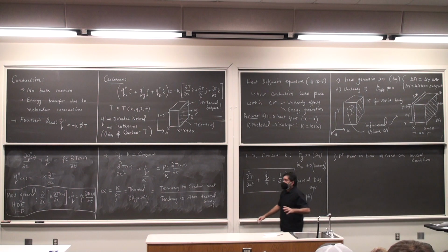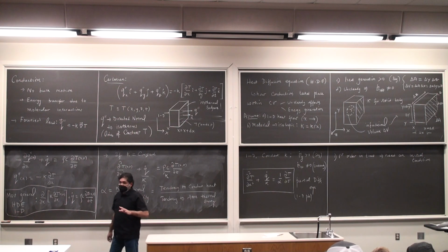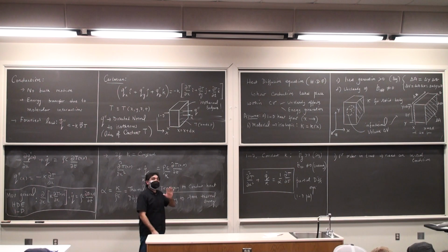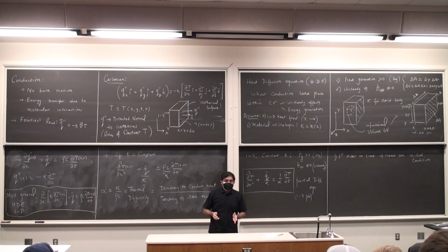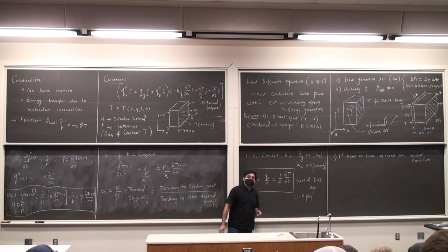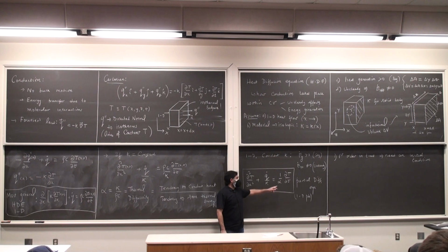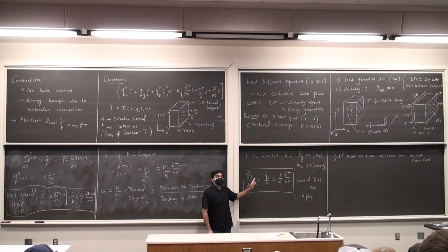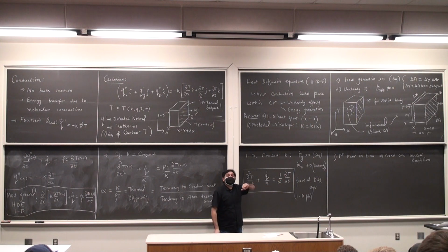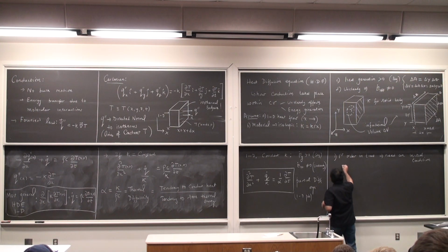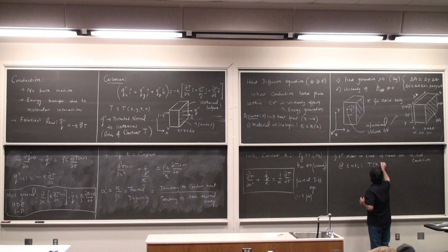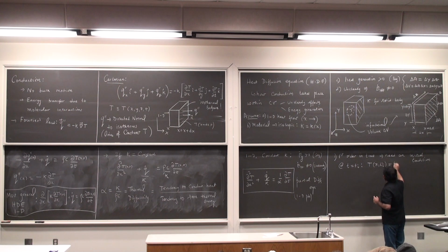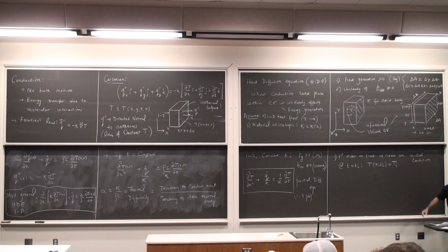What you would have done in system dynamics is you would have solved only ordinary differential equations, and they are all time dependent quantities, which means you will have to deal exclusively only with initial conditions, displacement condition, velocity condition, and so on. In our situation here, it's a little more complicated. It is not only a function of time, it's a function of space as well. So to have the time dependency taken care of, I need an initial condition. So at some time, the temperature is T is equal to Ti.